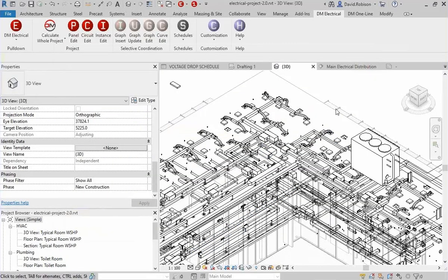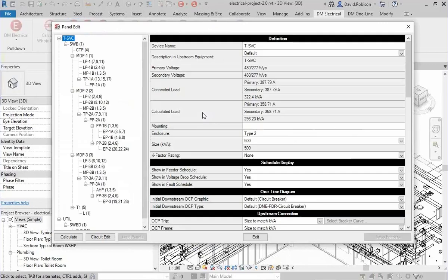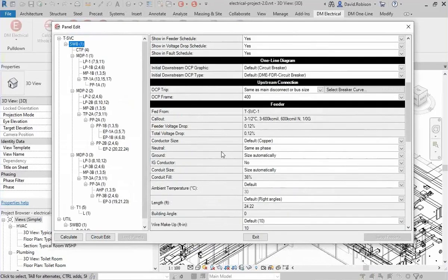And currently we do account for the wire ampacity in two different ways. The first is if you have a double neutral, we assume that the second neutral is going to be a carrying neutral. So it's going to have a current on it, so you need to derate your wires because at that point you've got over 3 wires with current in the conduit, so you need to derate by 80%.